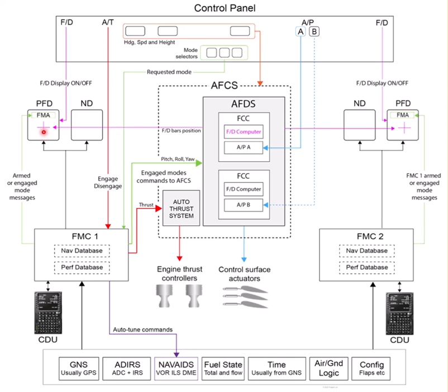But now what have you told the aircraft you want to do? That's down to the control panel at the top. So first of all, you've got to switch on the flight director, and if you have, then the flight director is going to look to see what modes you've selected on this panel.